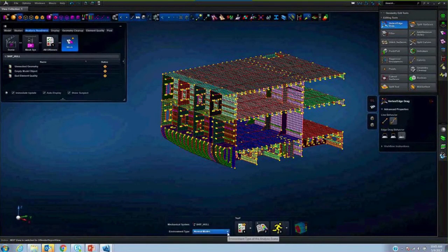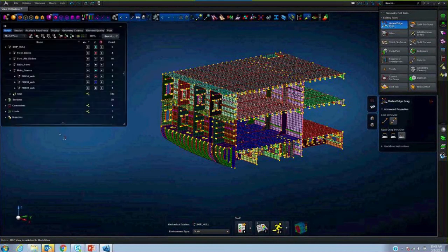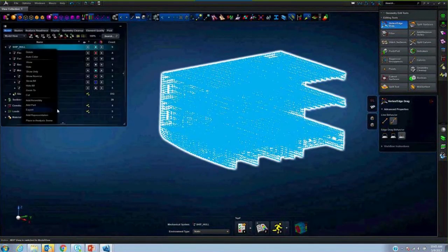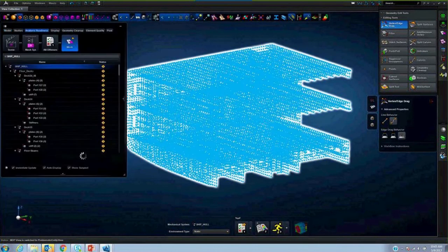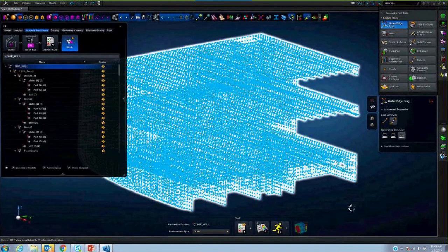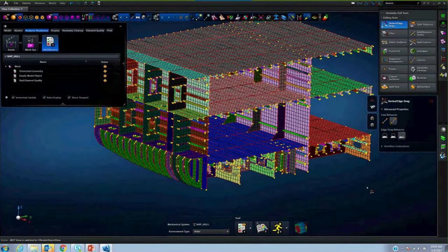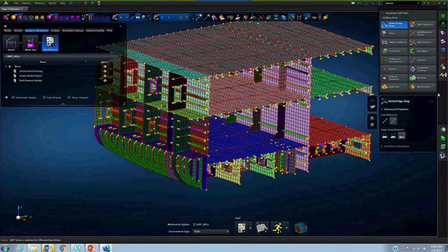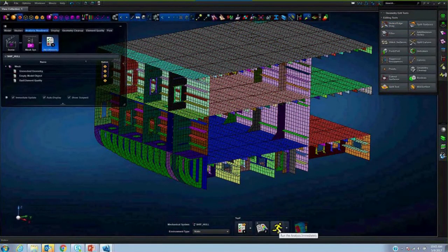And of course, now I need to set this to static analysis. Since I'm going to set this back to static analysis, I would rather make sure I set this context once again. With respect to static analysis, it has no other errors or warnings that we need to take care of. If you come back and see, it is ready to run. All right, now let's run this model, which may take about 3 to 3.5 minutes. Meanwhile, let's look at what other tools we have in Apex that help to build such a humongous model.